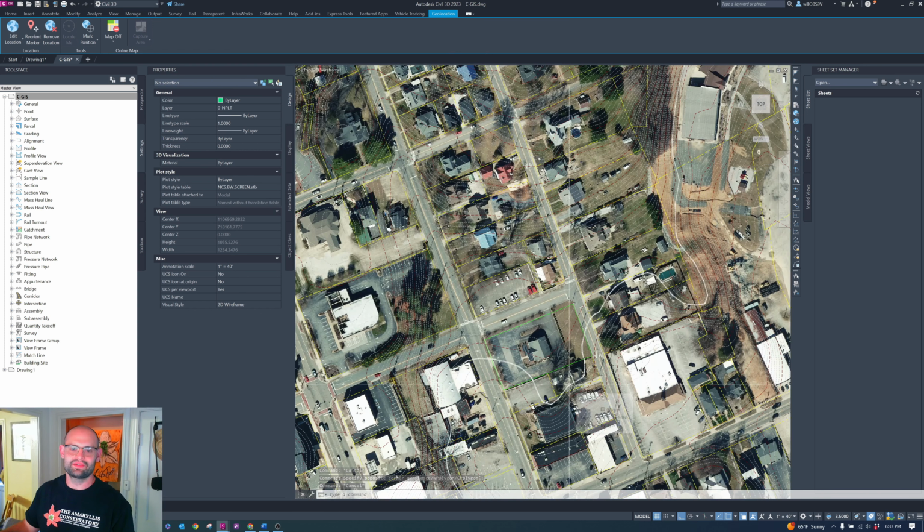At this point, we've got a good looking base map and we're ready to start our feasibility study. But to recap, let's start back with what GIS stands for. It means get it surveyed. Here we can answer big ticket items, but that's all we're doing, not completing a final design on this. And we're going to keep this file separate from our true survey file. We're also going to keep both of those files separate from our proposed line work file. And we will unify them through XREFs. This will keep us from tripping over ourselves and showing existing work as proposed and proposed as existing in any which way that we could mix things up.